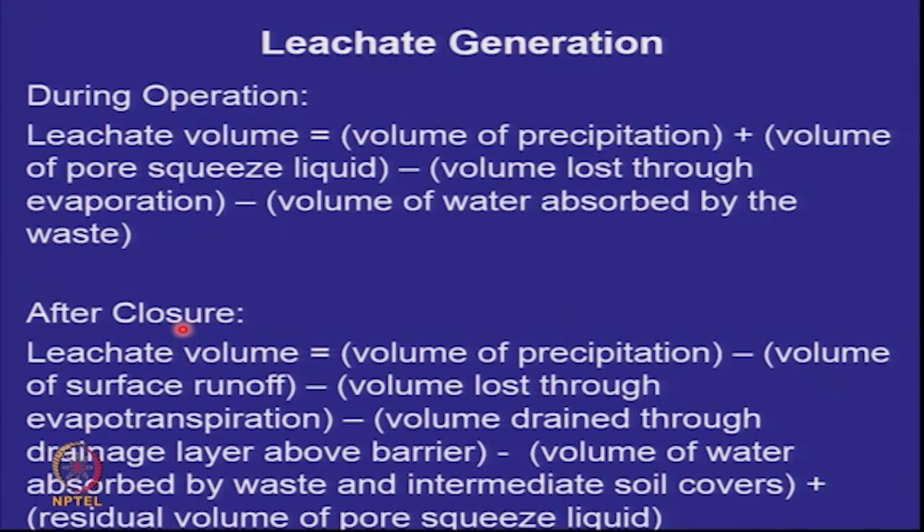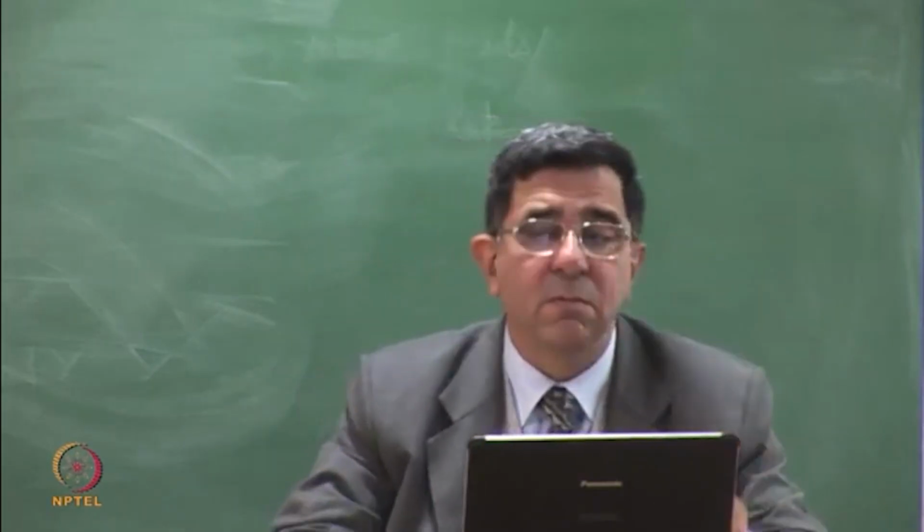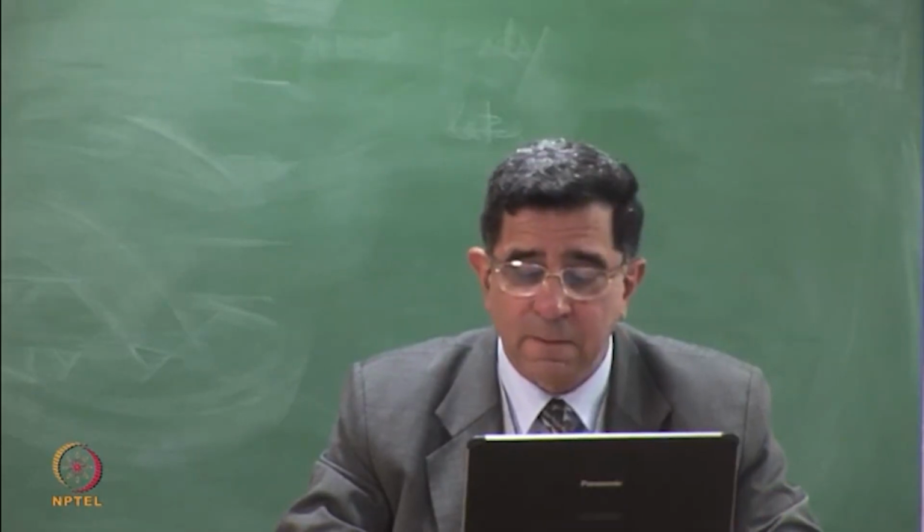After closure, volume of precipitation, minus volume of surface runoff, minus volume lost through evapotranspiration in the cover, minus volume drained through the lateral drainage layer above the barrier, minus volume of water absorbed by the waste and the intermediate soil covers, plus some residual volume of pore squeeze liquid. Mostly pore squeezing would have finished as the phase builds up, but there may be some pore squeeze liquid or some products of reaction taking place in a municipal solid waste landfill.